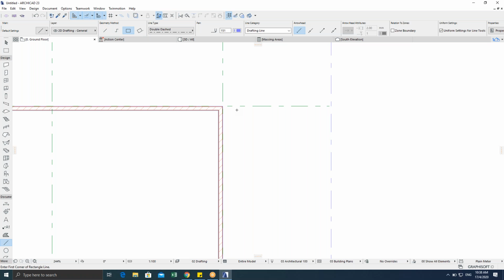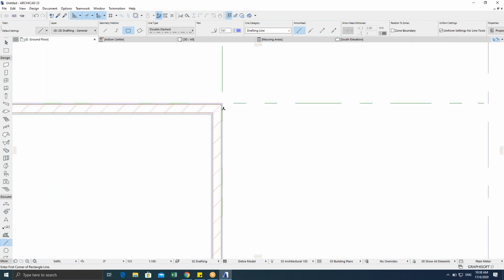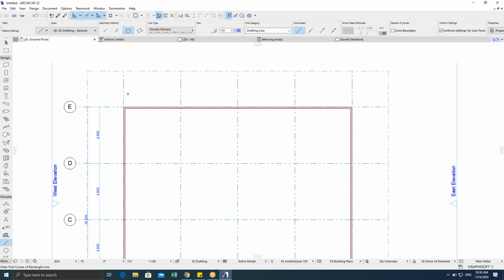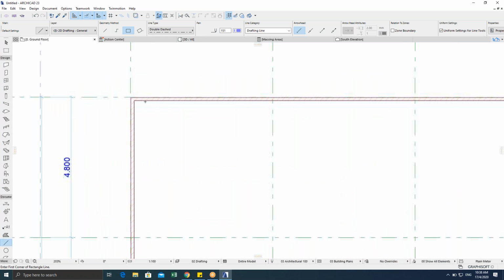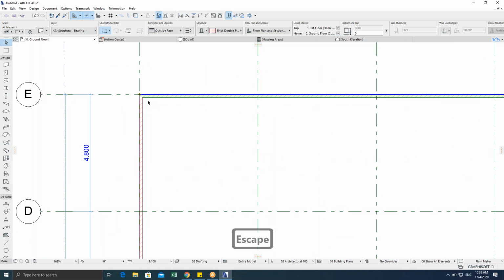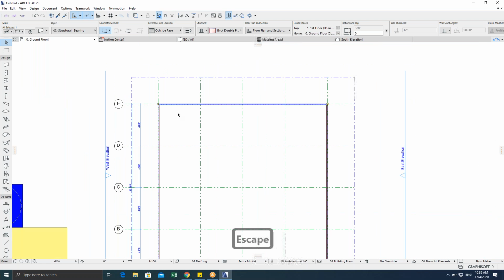It's supposed to be inside of the setback. Then you will get your correct setback from the boundary line. That's why I use this external wall as the outside face for the reference line location.